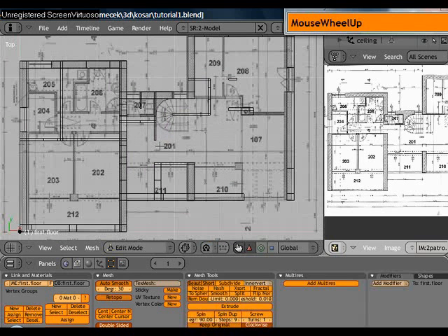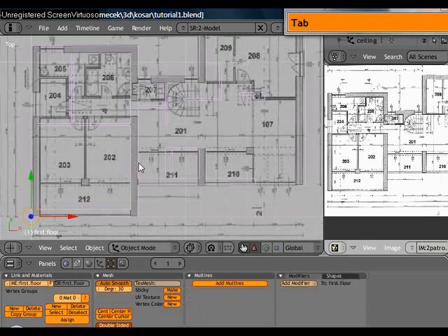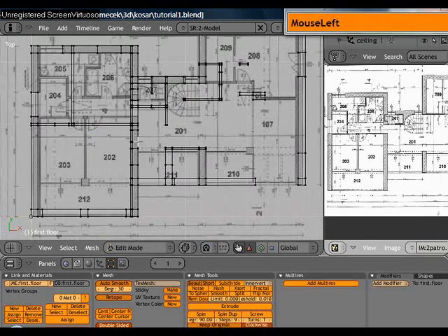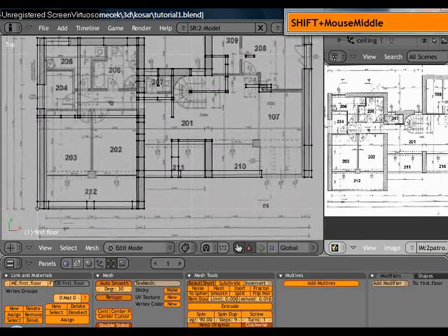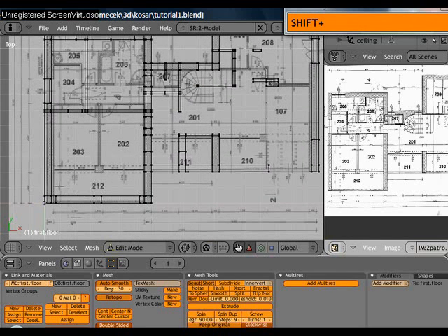And I'll go to object mode. I'll tap to edit mode, and I'll go to select vertices. So what I need to do now is adjust those vertices in here so they are where they should be. So in here, for example, I need to insert loops, and I need to align this one with this wall, G for grab, align this one with this wall.